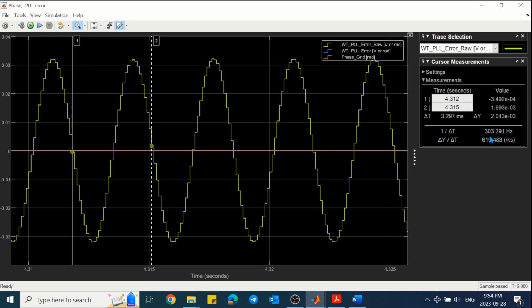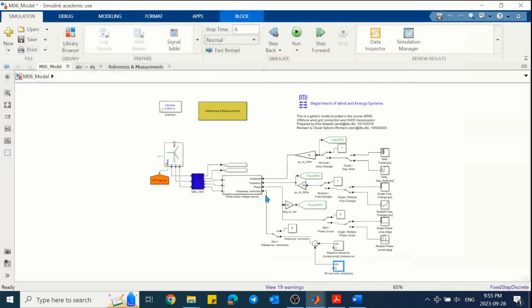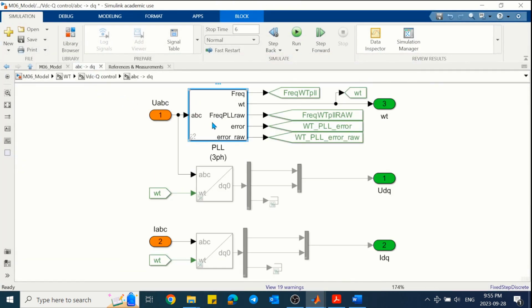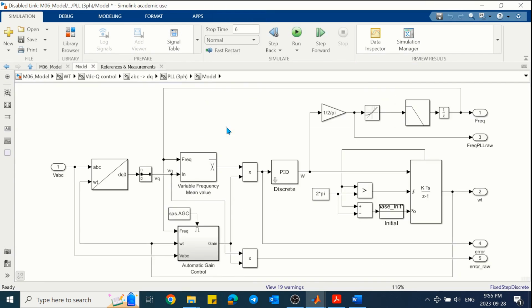And we know the reason, because the PLL is shifting back all the signals by one fundamental frequency, so all the harmonics will be minus 1. So a negative sequence, which is -1, will be -2, and the seventh harmonic will have a frequency equal to 6 harmonics in the DQ domain of the PLL.